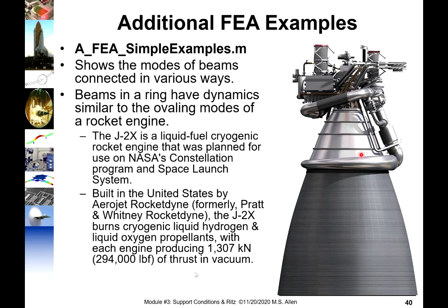This is the J2X engine, similar to a lot of others where there's fuel delivery system and combustion, and then a big nozzle. And the hot gases, after they burn, travel through this nozzle, and that causes them to accelerate. And for those of you who haven't had fluid mechanics, you think of a nozzle on your garden hose as being something that comes to a point to speed the flow up, right?